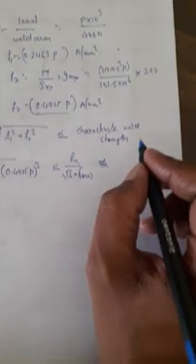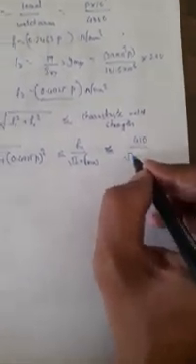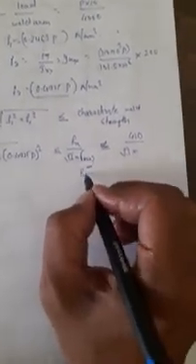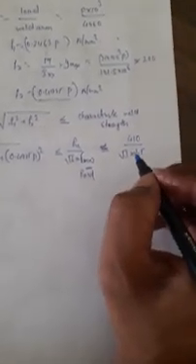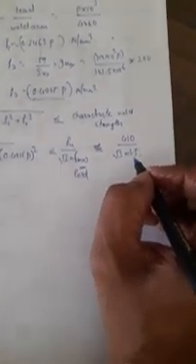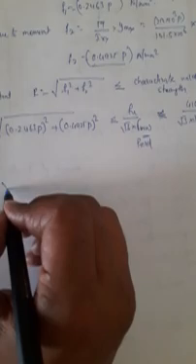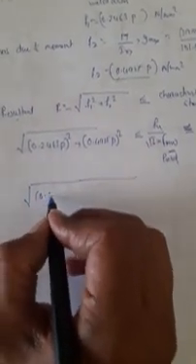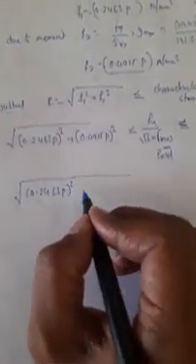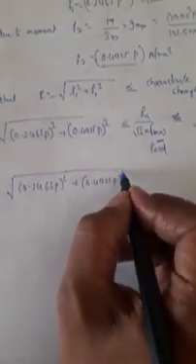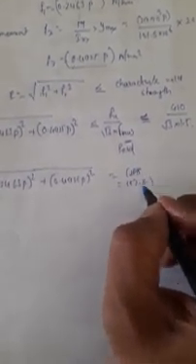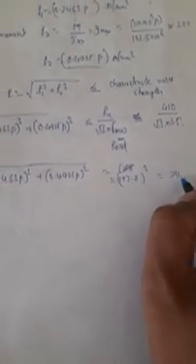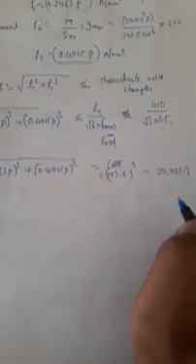So that I am going to substitute the values. 410 divided by root 3 into gamma mw. For field welds, gamma mw is 1.5. If we are going for shop welding, partial safety factor is 1.25. For field welds, gamma mw is 1.5. So I will get that equation as 0.2463 P bracket square plus 0.4925 P bracket square is equal to 157.8 bracket square, which is equal to 24903.7.